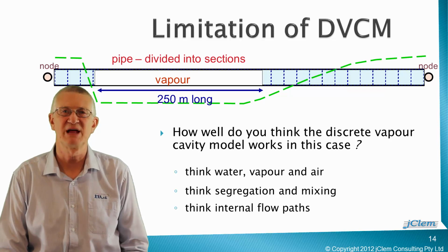In preparing your answer, consider that in that part of the pipeline at different points in time, fractions of a second apart, you may have a mixture of liquid water, water vapour, and dissolved air that has come out of solution. Develop an image of how you believe this mixture will be physically dispersed in this part of the pipeline. Think about how this mixture will move. Think about how this mixture is likely to behave when the pressure increases above vapour pressure in this part of the pipeline.